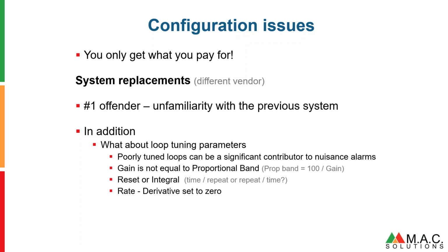Gain and proportional band in controllers are not the same. This vendor who did the return to normal, who set the deadbands incorrectly, on a different job, different plant, different country, different engineers, had the same issue. They copied the gain, reset, and rate values to proportional, integral, and derivative values. They took PI controllers and set them into their default PID controllers and set the rate action, the derivative, to 0, which stopped the controller from working instead of using a PI controller.